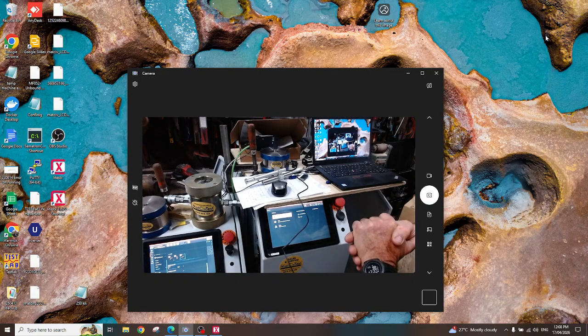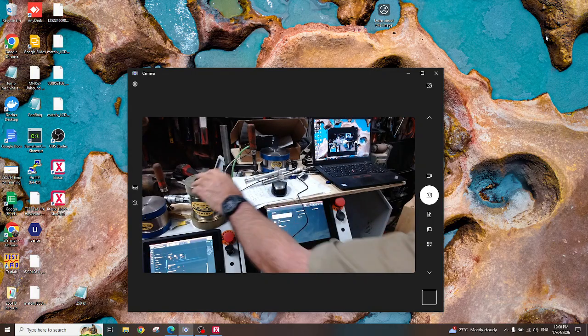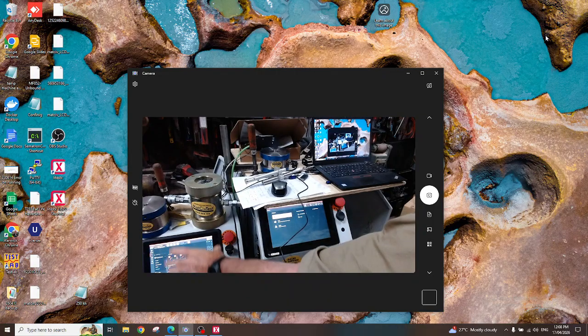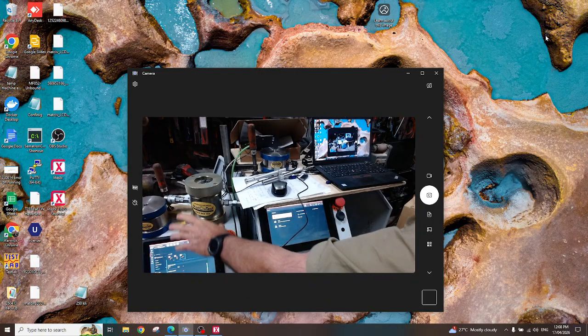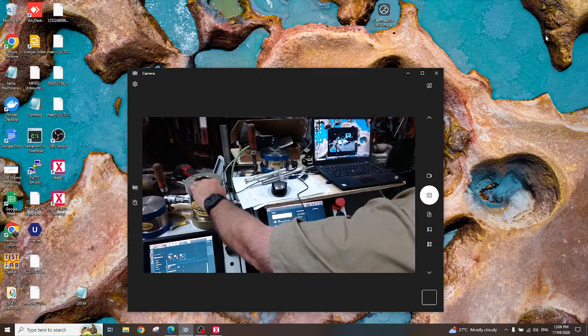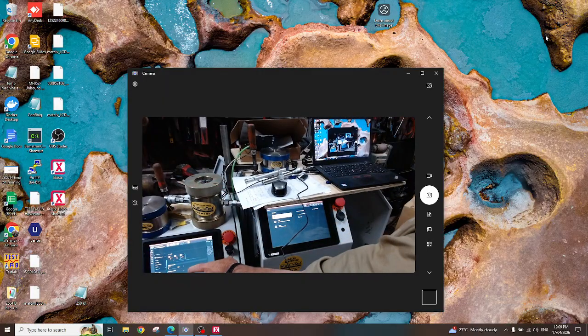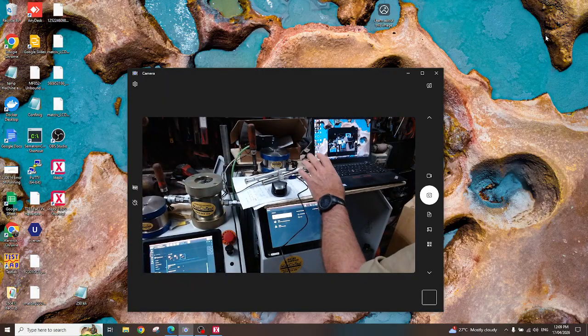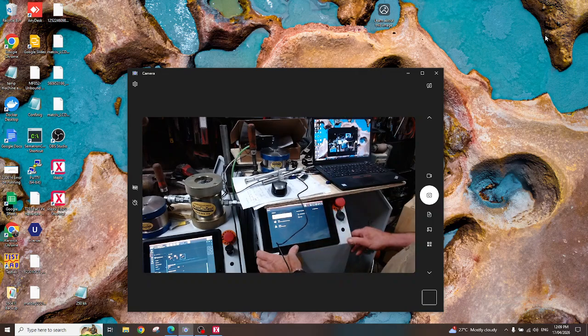They're putting the two pump units onto an existing load frame. One pump, this pump here, will be controlling confining pressure on a Hoek cell. Here's the Hoek cell, so that'll be hooked up to the Hoek cell. And this pump unit here will be controlling the axial load. These two pump units are connected together with a communication cable.